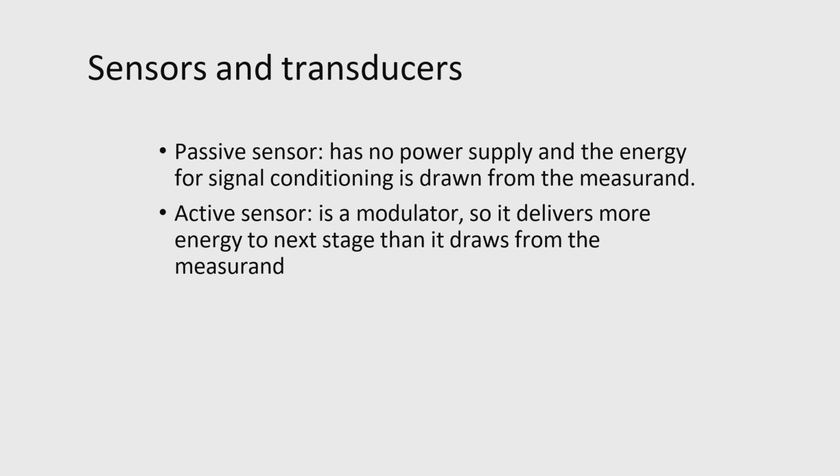If I put some load on a piezoelectric crystal, with the load it will get displaced, and that displacement or that strain we can sense, and then we can get an idea about the loading. But it can also be used as an actuator. That means if I give a signal, then with a small displacement it can actually do some work, or that small displacement later on can be amplified. So a sensor is just for sensing.